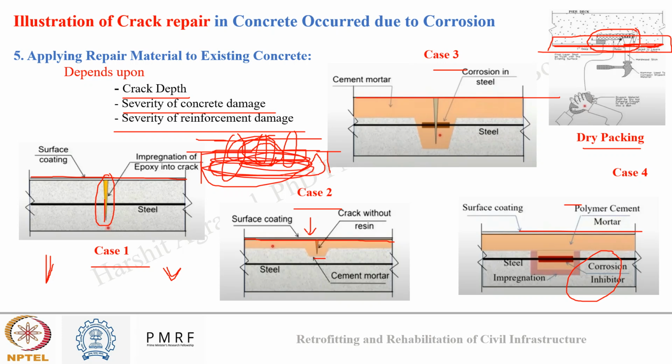So that is the only difficult part, sir. How to place? Practically, we are not getting any clearance. Suppose we want clearance, then again we have to damage the surface. Suppose the thickness of the slab is only 4 inch, then it is further getting damaged up to the top surface. I didn't understand your point. What you said is that the bottom surface you will clear and put a reinforcement, you can tie with the existing bars. Practically, that is not happening. Even suppose we drill somewhere, then again a leakage issue is coming.